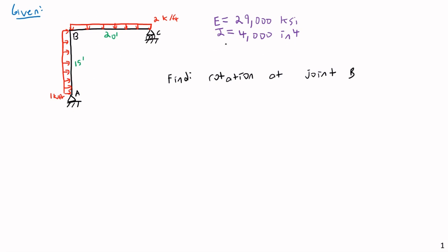Now, I am saying that both the column and the beam have the same cross section. In any real structure, that's very unrealistic. You're typically not going to use the same cross-section for your beams and your columns. That would be very unorthodox to say the least, and not very efficient, but that does make our calculations a little bit simpler. Realistically, you probably have a more compact shape for your column and a beam that's more optimized for bending, but let's not worry about such things for now.